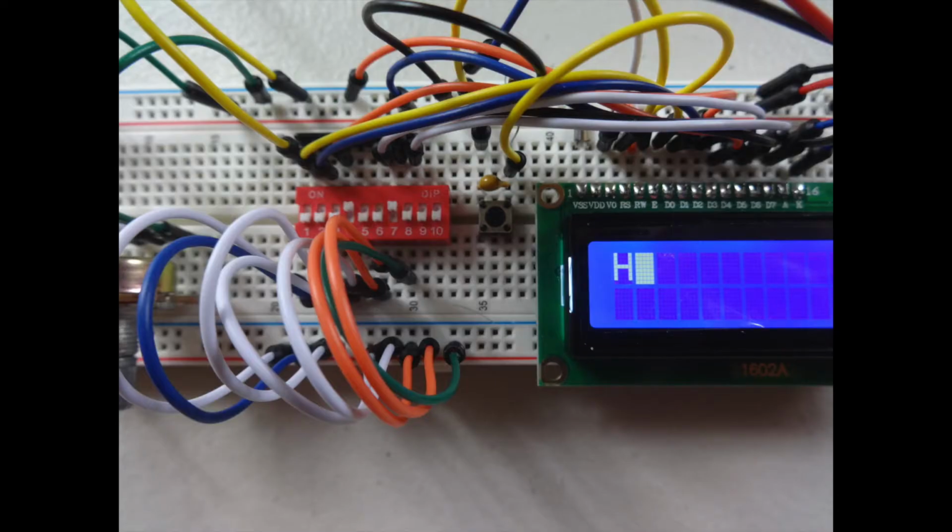Now one thing to note here is that on the LCD, the low order bit D0 is on the left side instead of on the right side. So what you'll have to do, depending on how your dip switch is wired, is to reverse it. So our dip switch number 1 is wired to D0. So in our case, you'll notice that we just reversed the dip switches, and then to send the data we hit the button. So here is the letter H displayed.